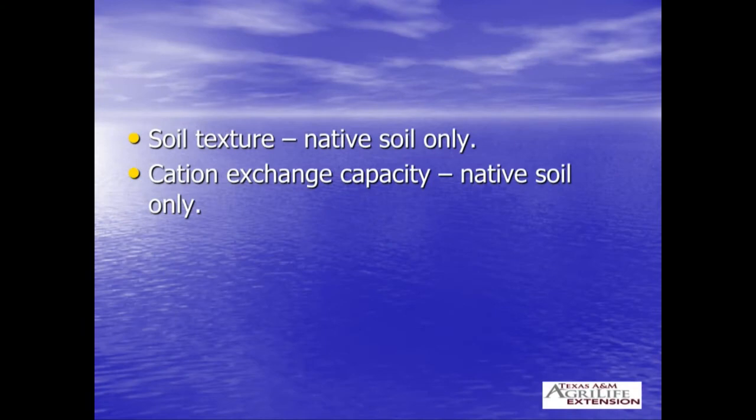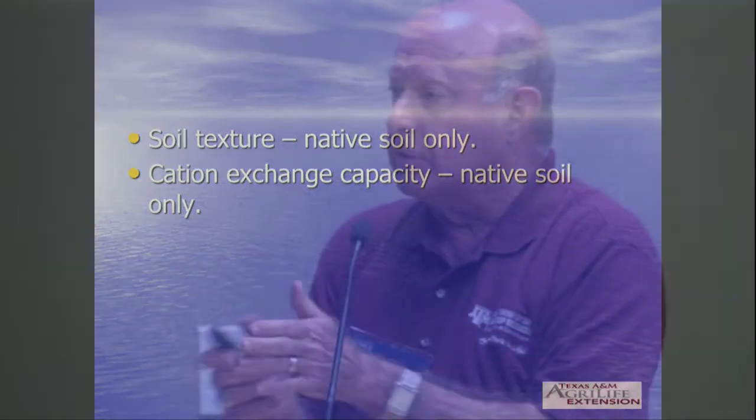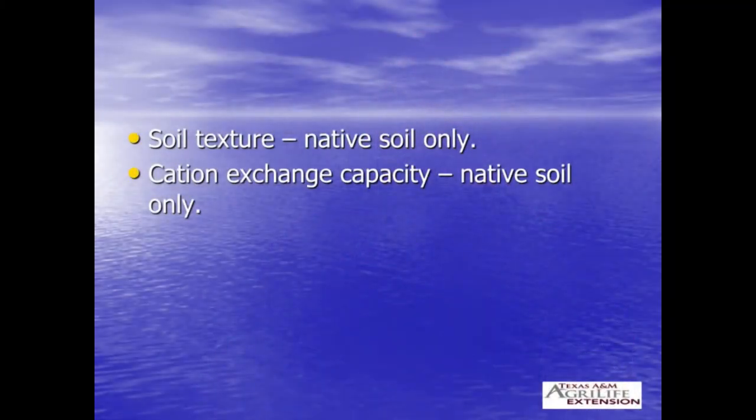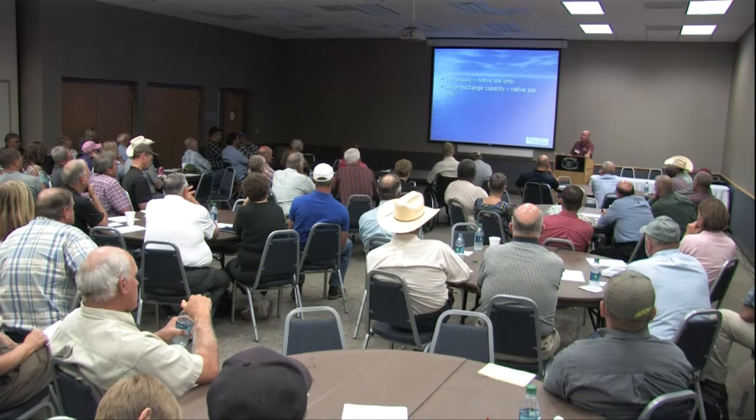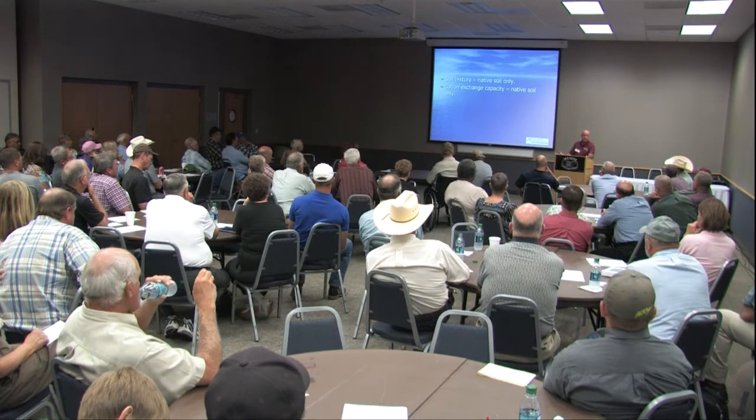Texture, you need to know the texture of your soil. If you're good enough, you can go out there and roll your little cigar between your thumb and forefinger and get the texture. Or if you've got a soil scientist out there working with you, they can get close enough that you don't have to pay for it. But you do need to know what texture you're starting with. And then I suggest you do the cation exchange capacity because, if you're adding that mud, it's going to change your cation exchange capacity, which is a good thing in sandy soils. It's not necessarily a good thing in your clayey soils. The primary reason is you don't need any more clay, more than likely. Adding clay to clay is not necessarily a good thing to do.